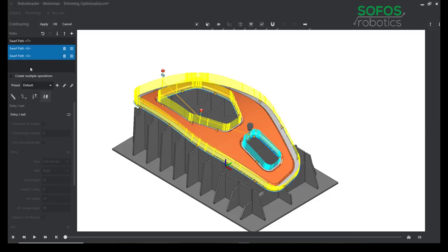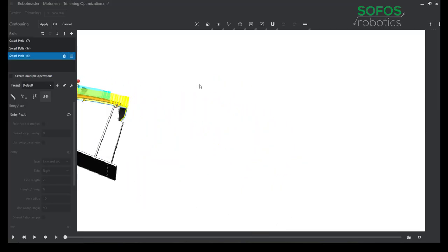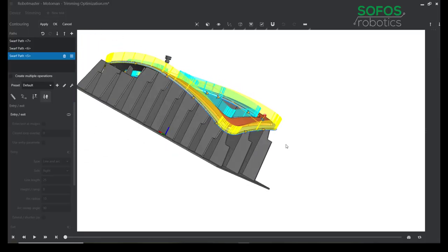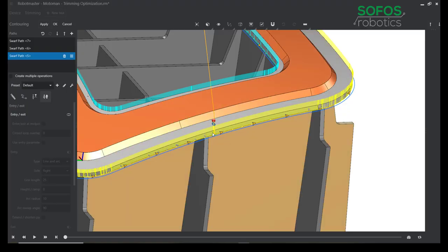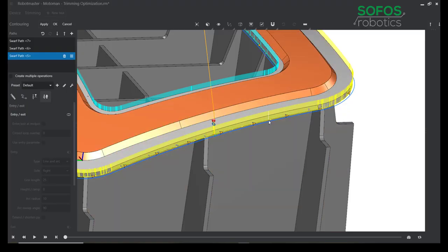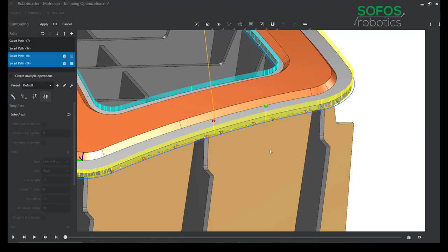One other thing I wanted to show you before we do that is, for instance, if you have a thermoform part or a plastic part that you get some warpage in, or you need to edit some section of it, you can come in here and left click, hold shift to highlight a certain section, and then right click there, go to path, and split that path.